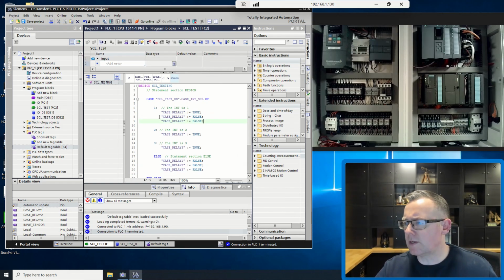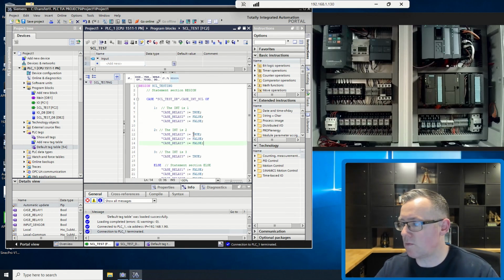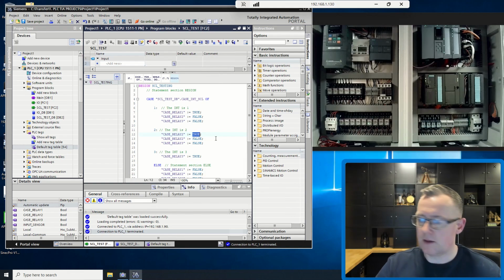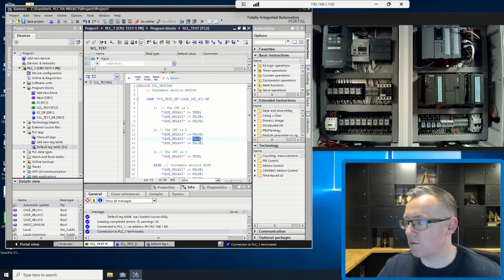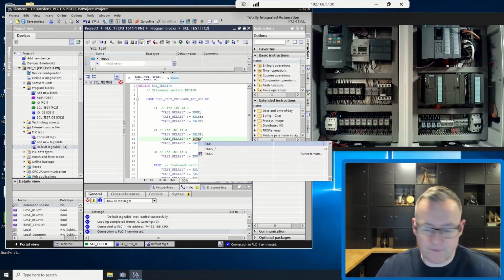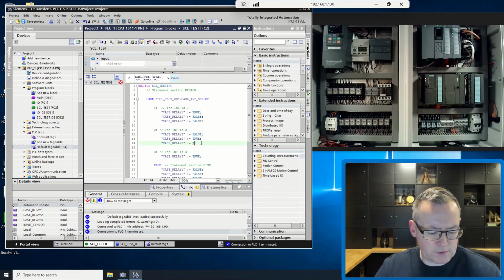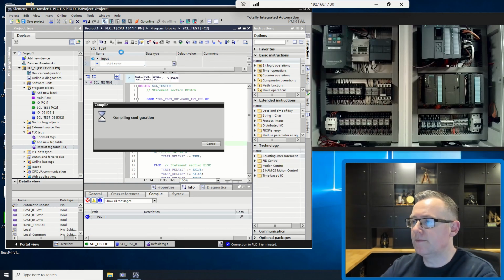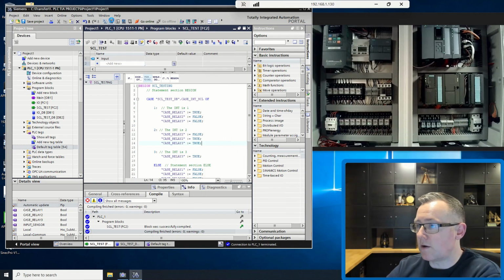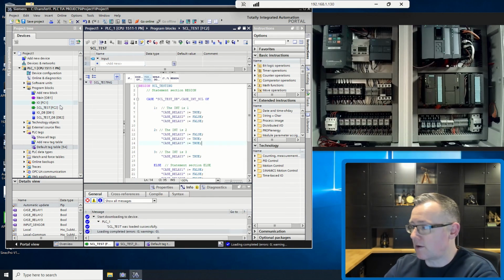Then maybe what we'll do is we'll have something here, and this is a very good analogy here, where we'll make this guy false, but then we'll make these guys true, and we can kind of jump back and forth just by specifying a number. So it's a very handy way to do things. So I'll just compile him again. And then we'll do a download again, just on the changes of logic that we have to that guy FC2.